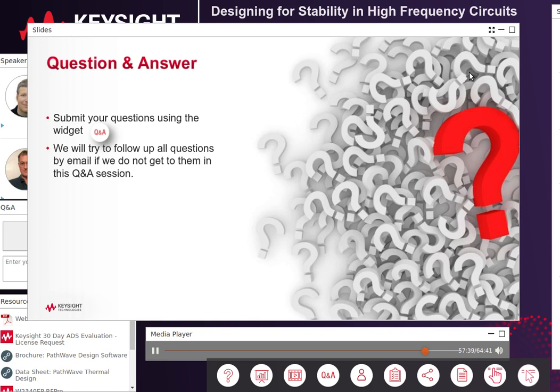So yes, the WS probe use is technically a local impedance stability approach, but any local method, when you sufficiently spread it through your circuit, effectively becomes global in its scope and its capability for all but the most extraordinary circuits. So, short summary: I use the driving point impedance and loop gain provided by the probe for my stability analysis and circuit design.